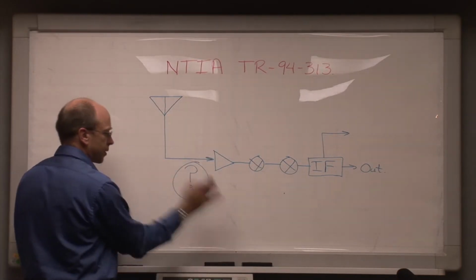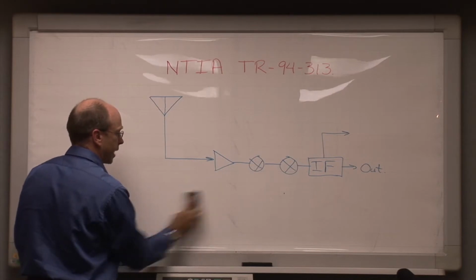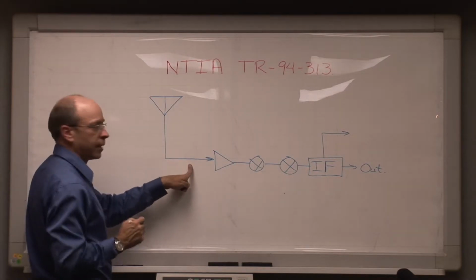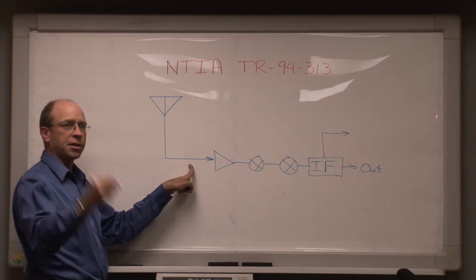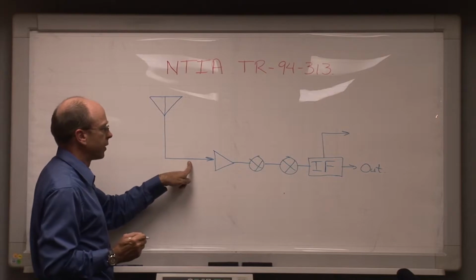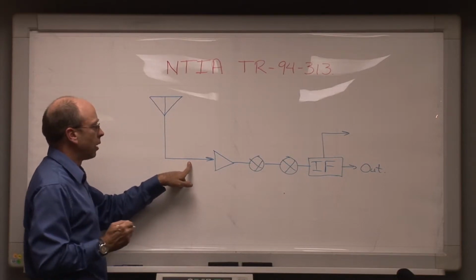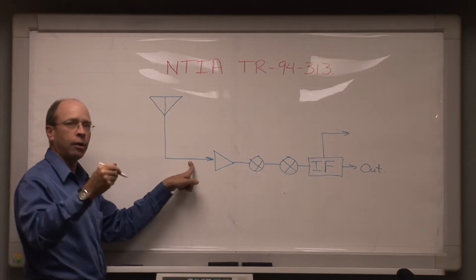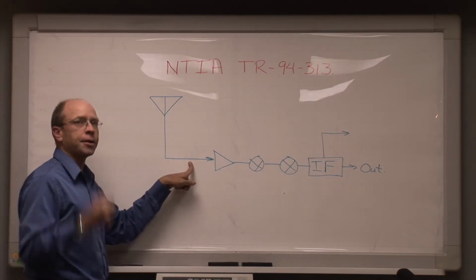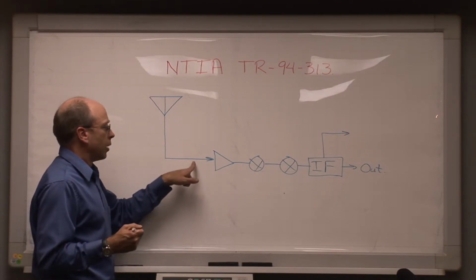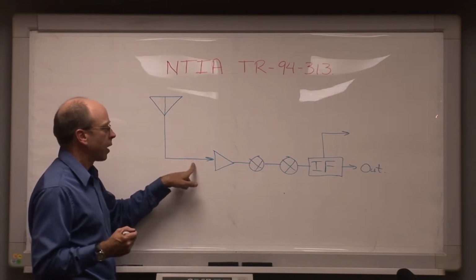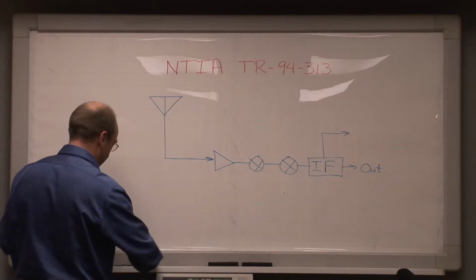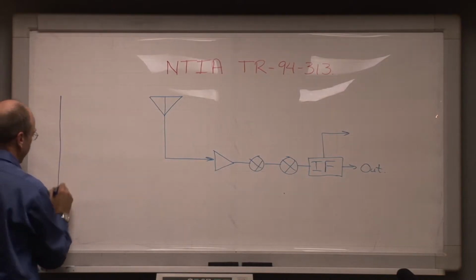If in fact you see that there's no bandpass filter or any other kind of filtering here at the RF front end, and you go then, as we discussed in the last talk, to the site, you make measurements, you look at the interference in the system, you work your way through the possibility that there's no interference occurring, you discover that yes, there is a transmitter involved, and you identify what the transmitter is, all of which we discussed in the last talk. You'll recall that the next step in the process is in fact to look at the emission spectrum of that transmitter and measure it.